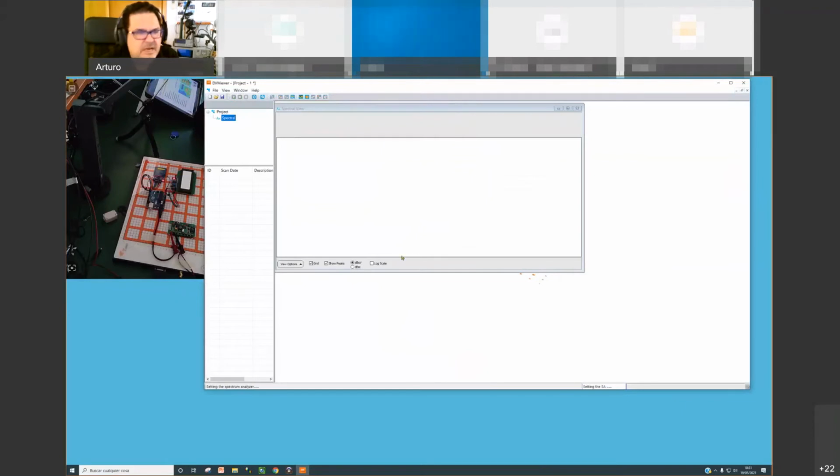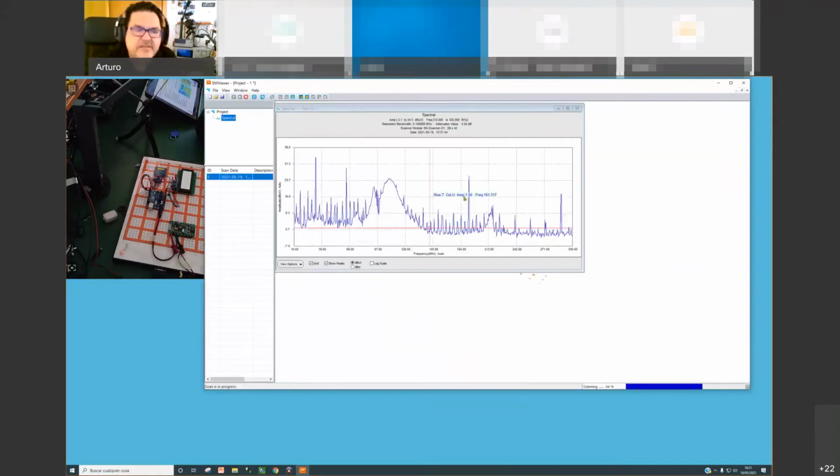So we will see now that the frequencies coming from the Arduino board are the frequencies you see now on the screen. Start. The system is on. Okay, you can see that I can identify here a frequency of 32 megahertz, a frequency of 64 megahertz, this frequency here. These frequencies are the 32 megahertz from the 2 clocks in my PC board and some of the harmonics. Look at this circle. This circle is because the software has detected they are the 2 most important peaks.